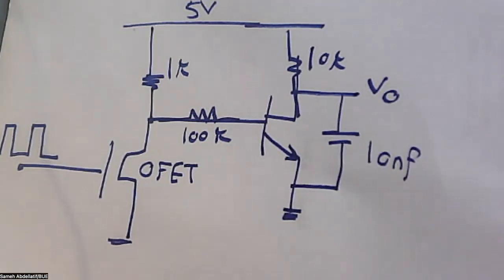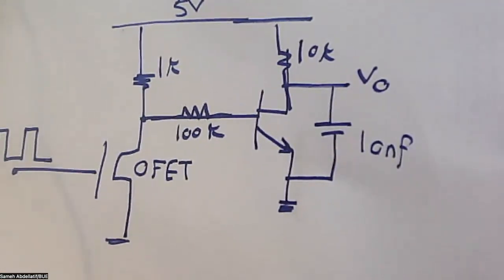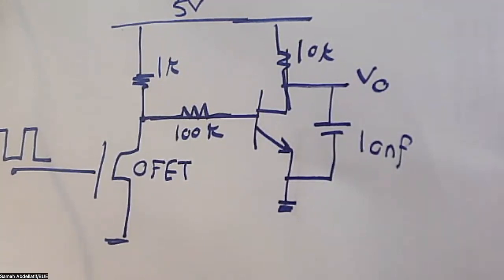Basically, my dear students, it's not a perfect on-off process, because simply, as we already studied, whenever the transistor is in the off state, it still consumes some power due to the off current. I think we already highlighted the parameters like the on-off current ratio and the subthreshold swing and all this stuff.